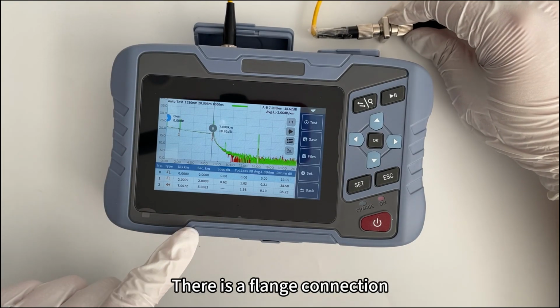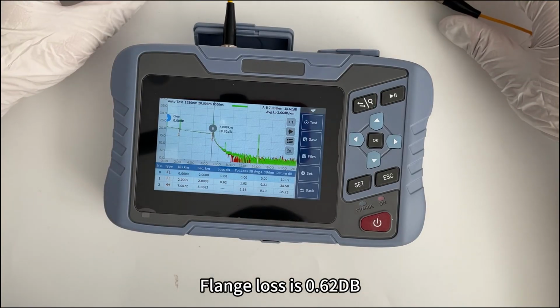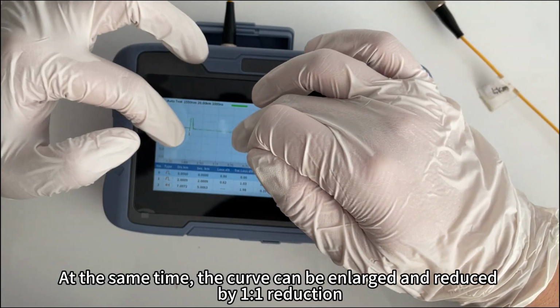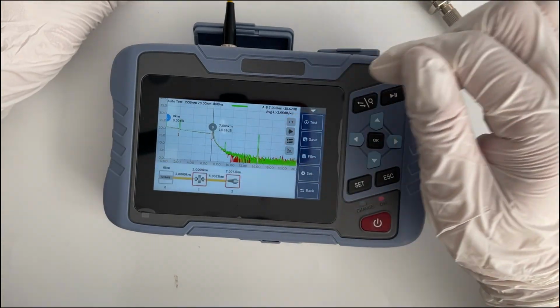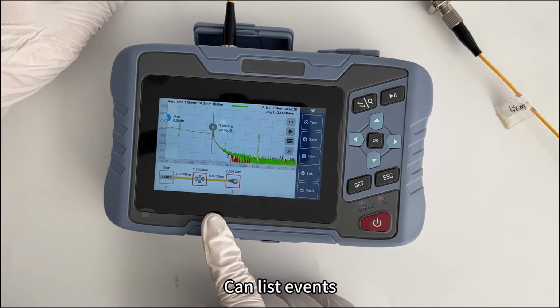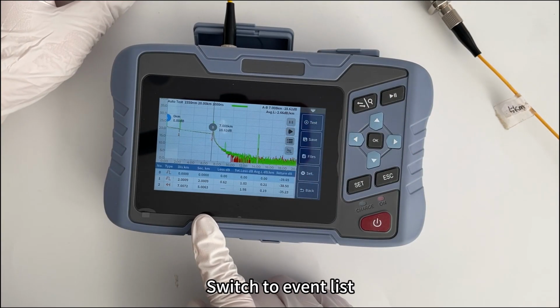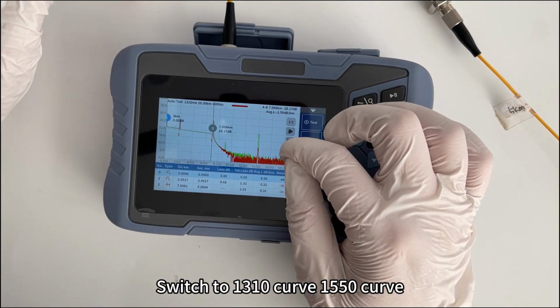There is a flange connection. Flange loss is 0.62 dB. At the same time, the curve can be enlarged and reduced by 1-to-1 reduction. It can list events, which is something we can visualize. Switch to event list. Switch to 1310 curve, 1550 curve.